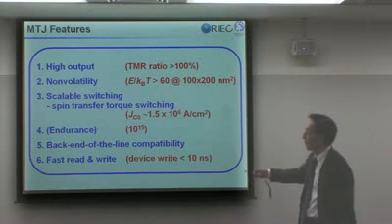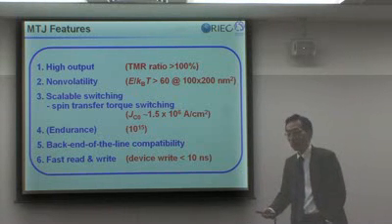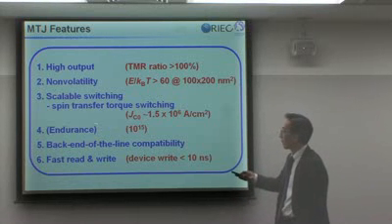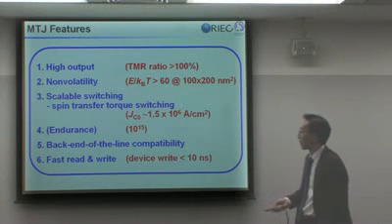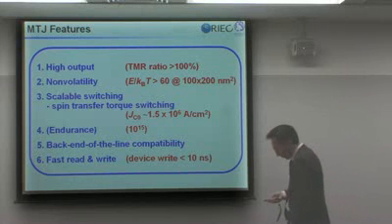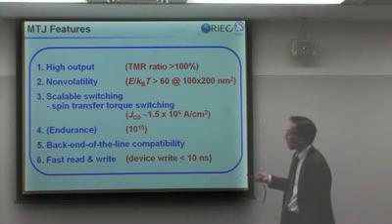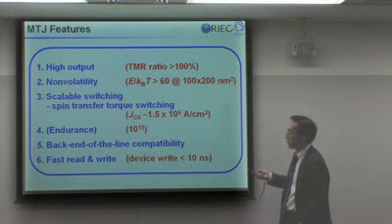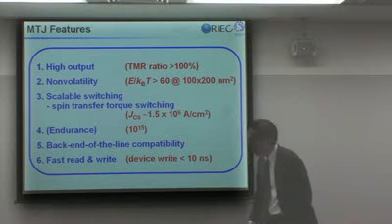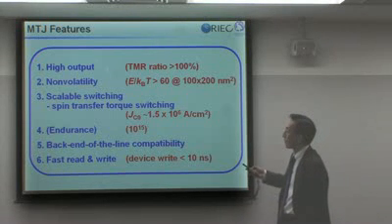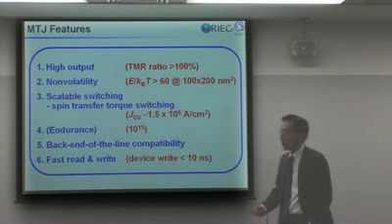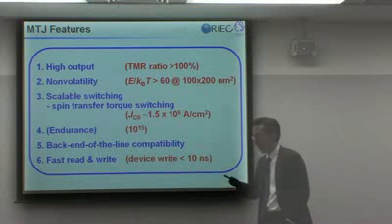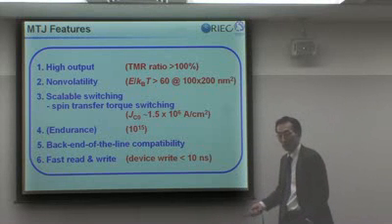So this is a rather unique set of features that you cannot achieve in other non-volatile memory elements, like flash. Flash endurance is not as good. FeRAM, it's rather big, and also it cannot scale down with the dimensions. So this is the only non-volatile memory element that you can use with logic integrated circuits that I will discuss in the following.